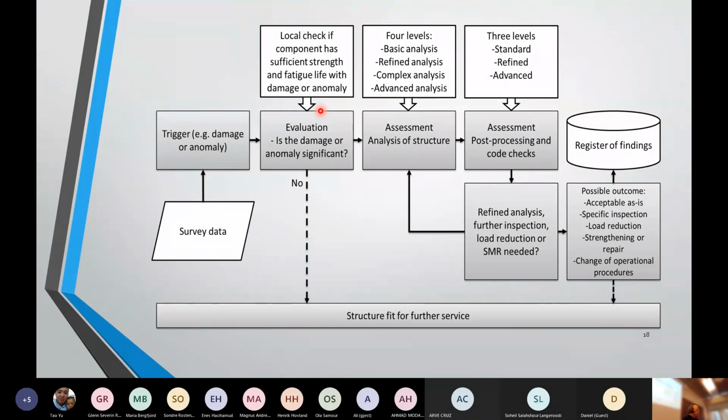If you are doing your design of a steel beam, you will, I guess, often try to have the utilization be like 0.999. Will that be your ideal? So when you do the code check, will you optimize or will you leave some extra strength in?